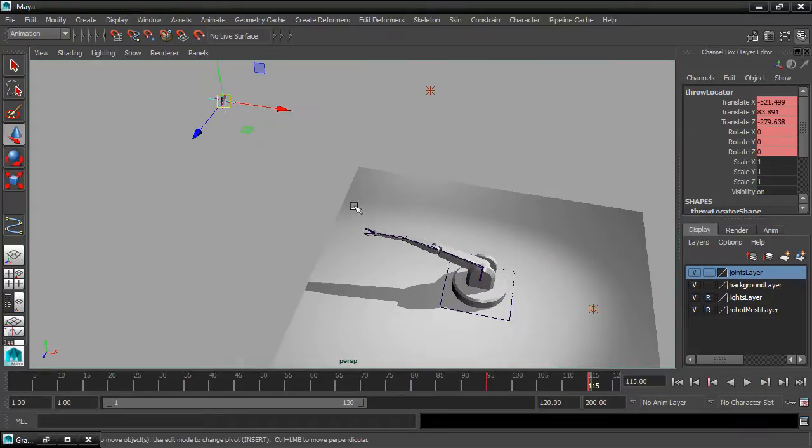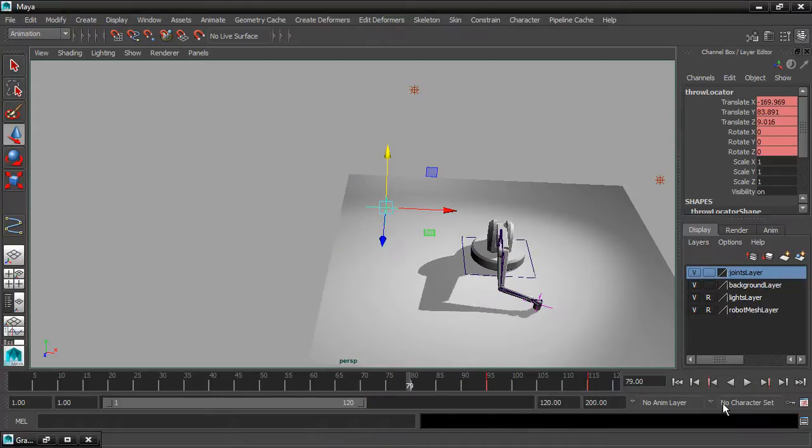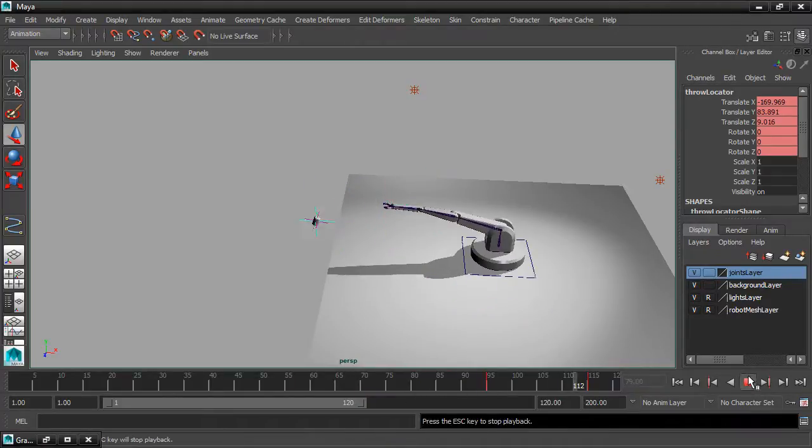Maybe it's flying too far and I can bring it back. I can park it at frame 115 and just move it closer. And maybe move it down a bit. And Shift W and Shift E on top of that keyframe will actually overwrite those values. And if I want to move more quickly, once again, Shift Select and move the keyframes earlier.